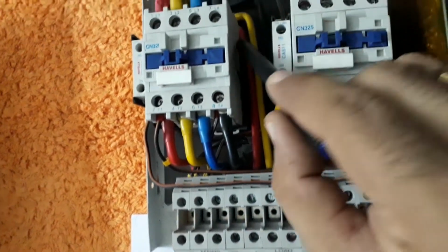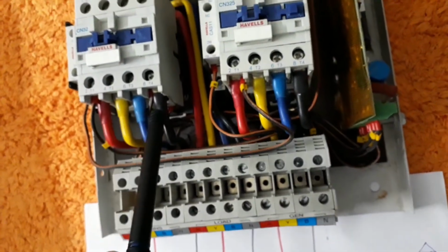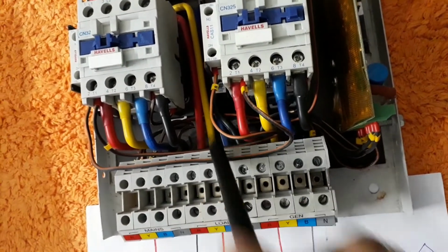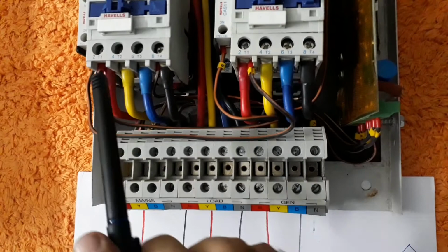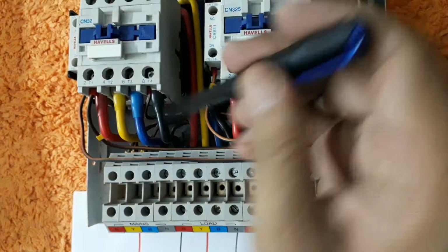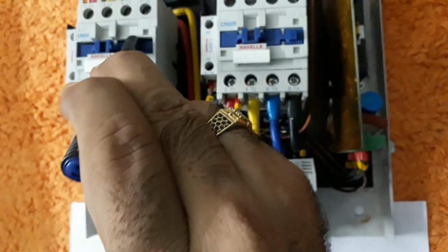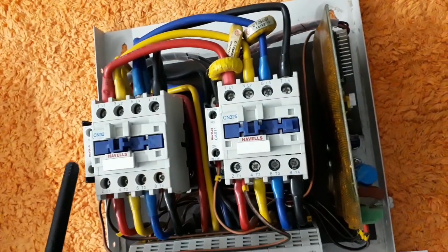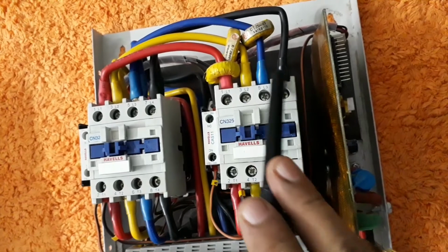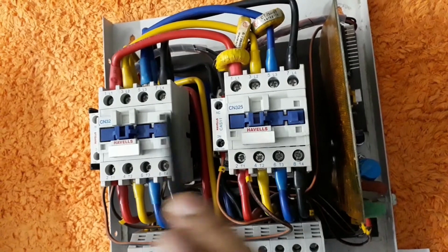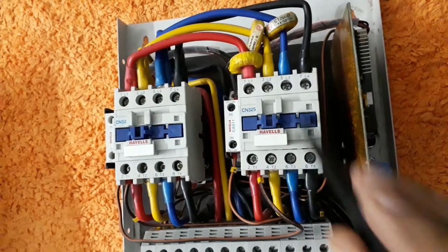If you see, these 4 wires are going to our house. So on one side we have the mains connection, on one side we have the DG connection, and in the center we have the connection for our house. Initially the mains is connected to our house. In that condition, this will be on, and when it is on, this switch gets off, so it keeps this circuit breaker in off condition. So when the mains is on, the DG will be disconnected from this line.